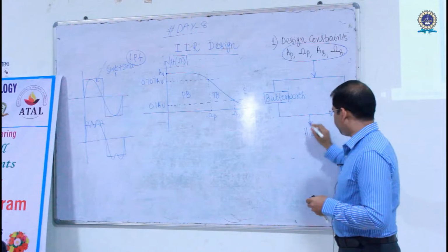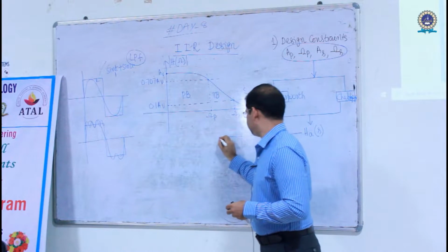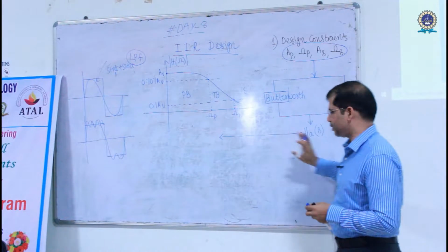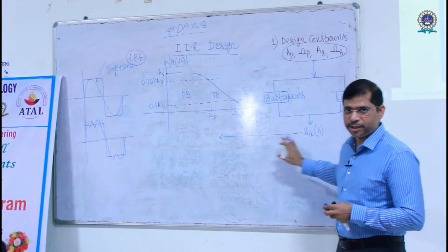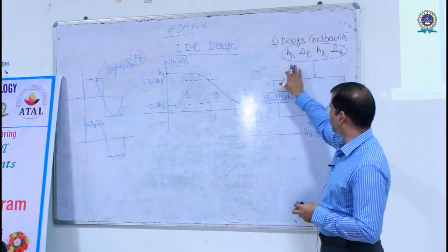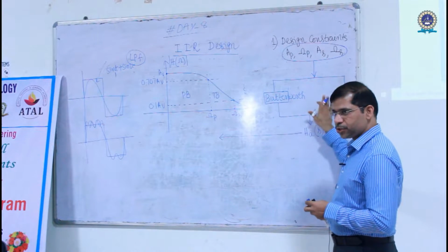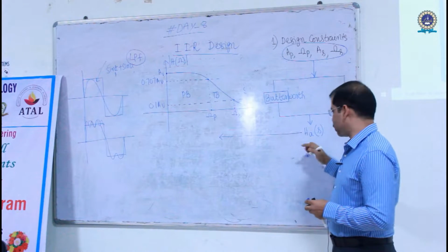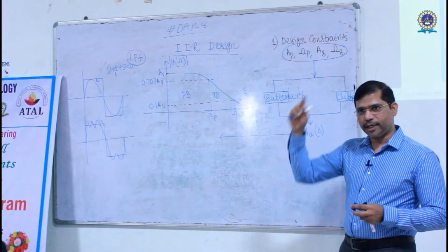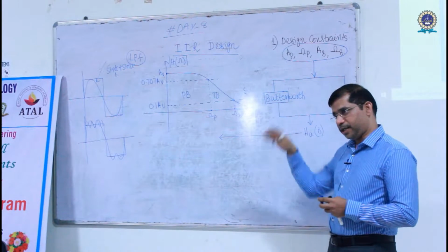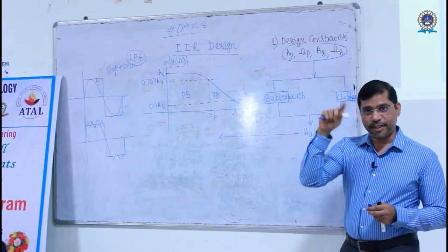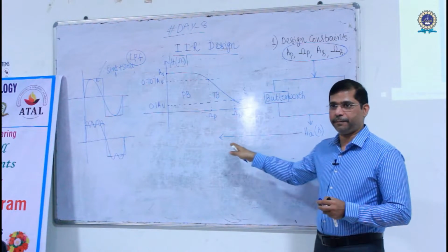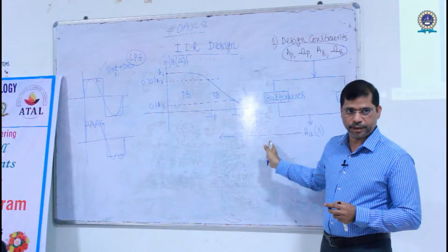Now you need to stop here and move to control systems, and apply all these stability techniques and verify whether this system is stable or unstable. If it is unstable, then you have to stop here, go back, change the design constraints, again apply these two techniques and then come. It has to go like this. You should not proceed further, because if you miss here, then you get h of z after 4 or 5 steps, and there you have to apply the stability techniques in the digital domain, which are the toughest compared to this, whereas here you have the easiest techniques in control systems.